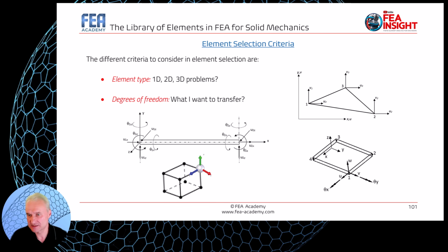Solid elements, as we saw before, generally have only 3 translational degrees of freedom per node, since the rotations are accomplished thanks to translation of groups of nodes relative to other nodes. However, beam and shell elements have 6 degrees of freedom per node.